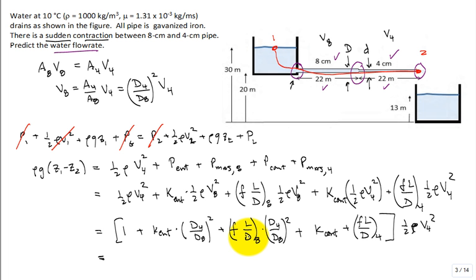Now, I already know the answer, I solved the problem already, so the velocity coming out the end, V4, the final answer is going to be around 3.3 meters per second. You don't have to be clairvoyant. You don't have to have a great guess on it. It's probably best to just get a friction factor, 0.02, and run with it.